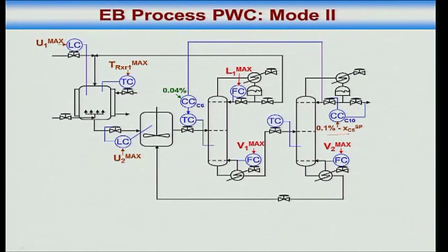Okay, then you see I am limited in my capacity to boil off. V2 max is max. I cannot boil off ethyl benzene. So if I am getting more ethyl benzene than I can boil off in the column, where will that ethyl benzene go? It will drop down and build up in the DEB recycle loop. Yes or no? I don't want to do that. So what do I do? I control a stripping tray temperature by adjusting the feed. That will ensure the feed is only so much, no ethyl benzene drops down. That makes sense? Okay, so that's what this temperature is. Now I have done this. That is a stabilization issue.